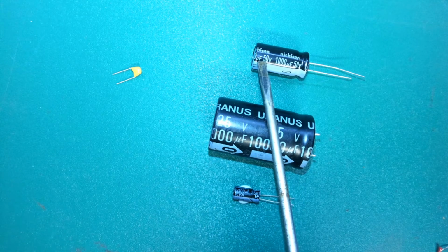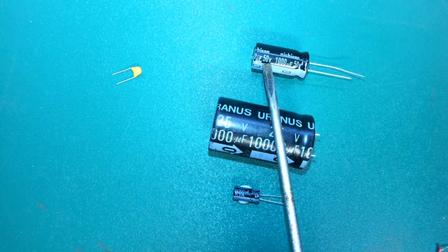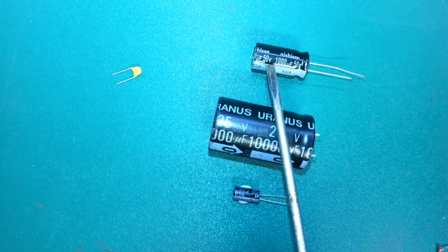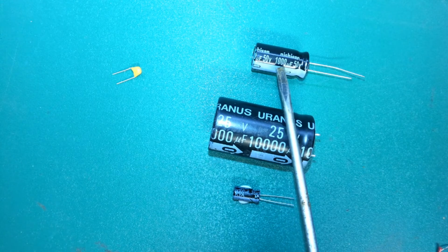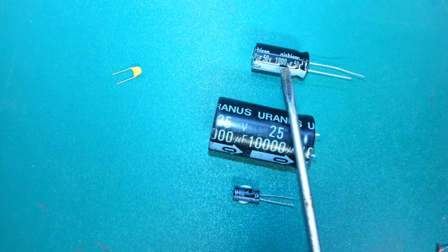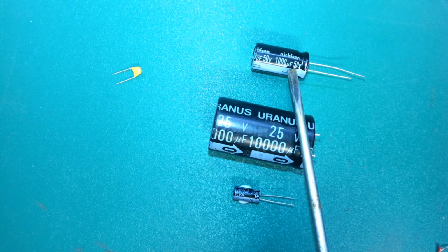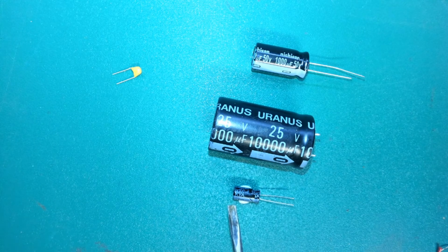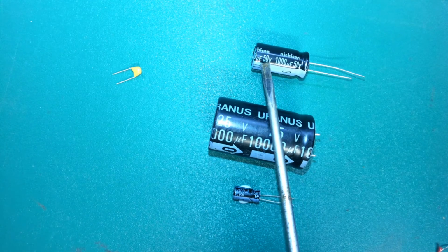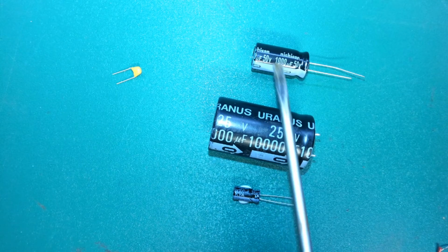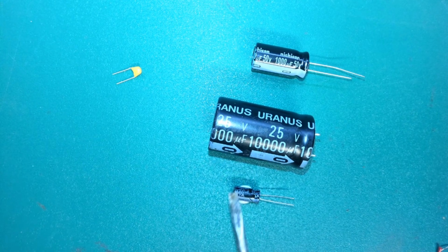And if you have a look on this capacitor here, you can see that there's a maximum voltage rating. This one is rated to 50 volts, which means that if you're only putting 5 volts through it, it'll work just fine. But if you put 50 volts through it, well, that takes it to its limit. And if you put 51 volts through it, well, it'll probably work for a while, but it will die eventually. Now, if you apply too much voltage to them, they'll probably break down slowly over time. If you hook up a polarized capacitor the wrong way, well, you can get a spectacular failure, like this.